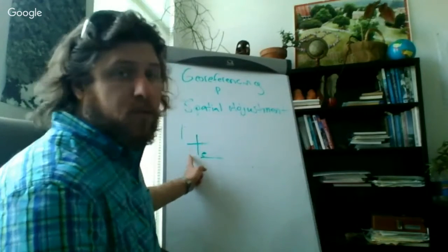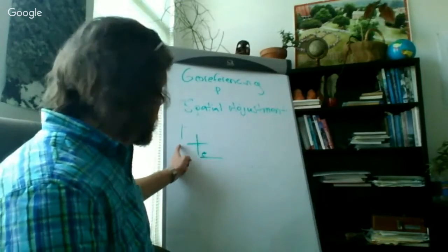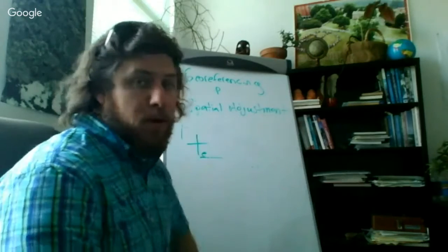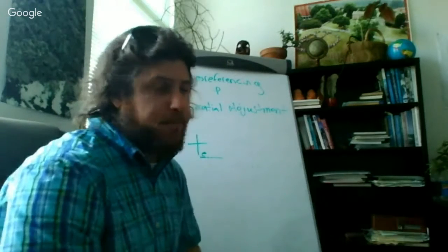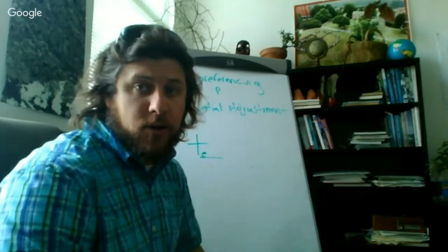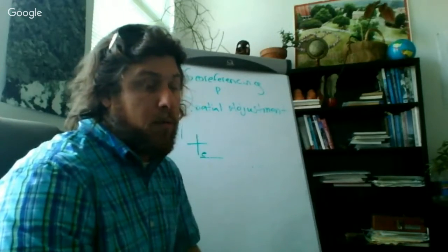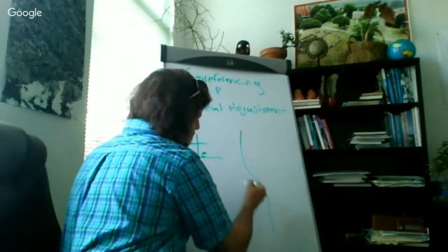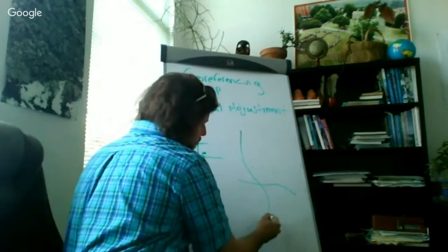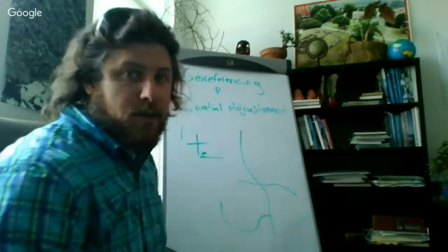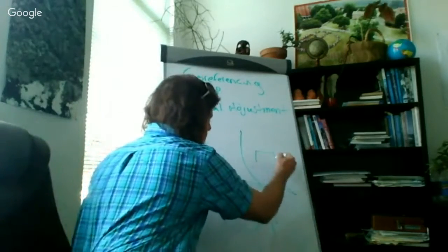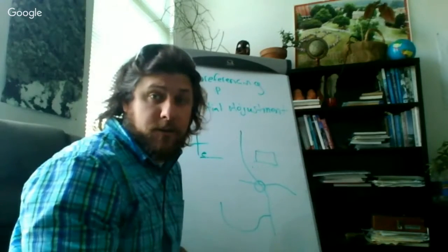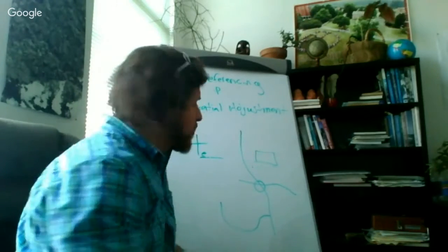So we can look for places where we have reference markers that give us information about that coordinate, or if we're not dealing with a topo map, but something that we've hand drawn in the field, or maybe something as simple as a road map, we want to look for spots that are really easy to identify. Oftentimes the intersection of a road is something that we can use to do georeferencing operations.